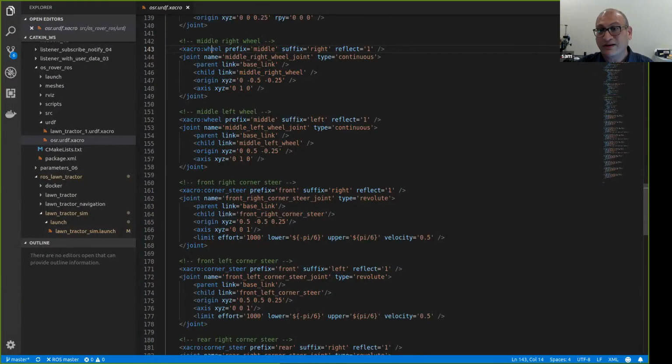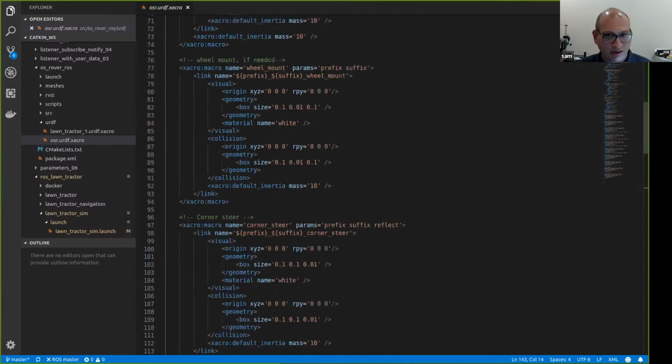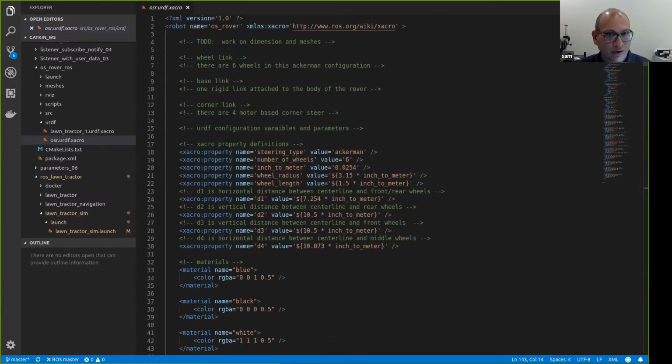Internally they pass this to their own format, and then they read it. But the xacro is basically like the macro program, so it has to convert back to the URDF. So you're simply using the URDF. You don't have to use .urdf.xacro. But .urdf.xacro means that when you convert it and check the links, you just see that in the URDF.